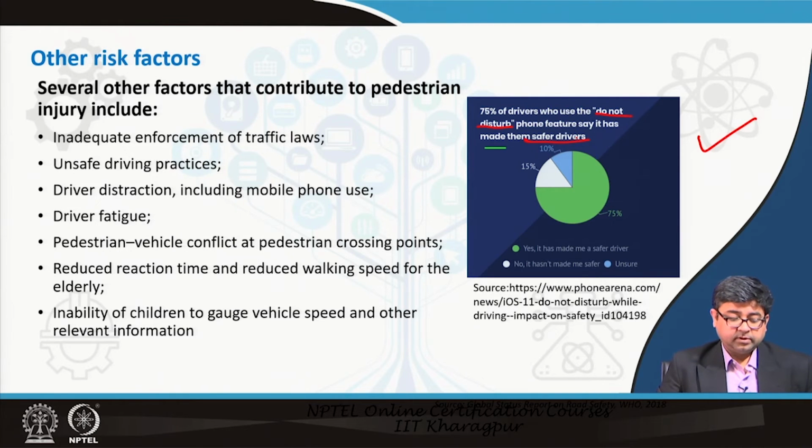safety conditions of pedestrians. Driver fatigue is a very important thing, especially we notice this among truck drivers who drive for a longer period of time. So there is always a relaxation time built into their schedules, so that they do not drive more than 8 hours a day or so, because due to fatigue, again your reaction time increases and you are not able to react in time to avert a dangerous situation.